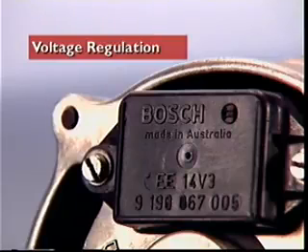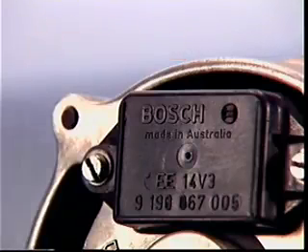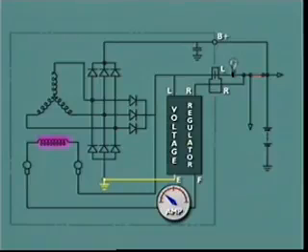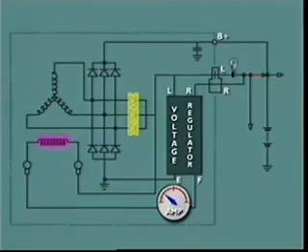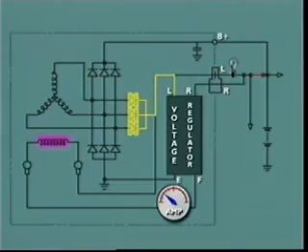This section examines alternator voltage regulation. When the engine is running and voltage output is low, the regulator switches the rotor circuit to ground and maximum current flows through the rotor field winding. The high-intensity magnetic field created raises the value of the induced voltage in the stator windings and alternator output rises. The output voltage is also impressed on the excited diode circuit, and the output voltage is sensed by the regulator control circuits via the regulator L terminal.